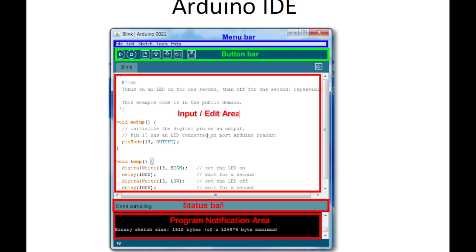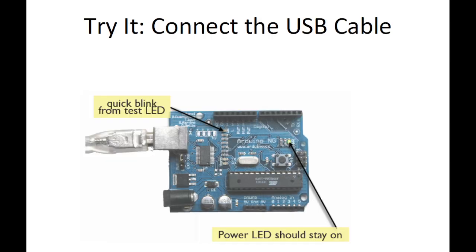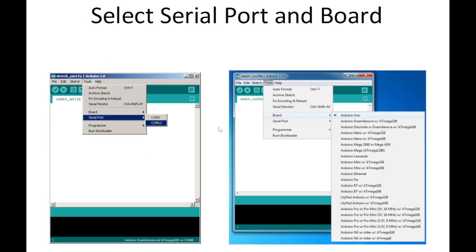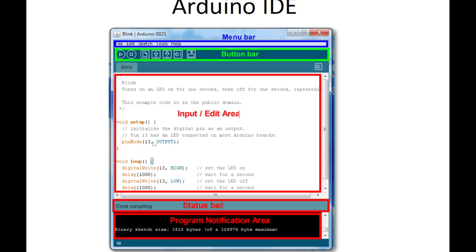Okay, but if you don't want pin 13, you will use the internal LED. There is a project in the sketch examples. Within there you will open it, and let's say you simply want to blink this internal LED. You just need to type internal LED or onboard LED, and the variable is already defined. You will see in that example sketch what it is, and you simply make it an output.